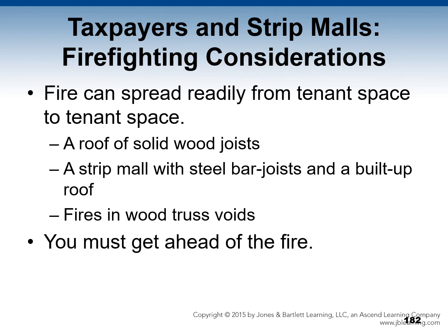Some considerations in terms of firefighting. Remember that the fire can spread readily from tenant space to tenant space. A roof of solid wood joists with a drop ceiling below will allow fire to spread in this void space. A strip mall with steel bar joists and a built-up roof can be subject to a metal deck roof fire.